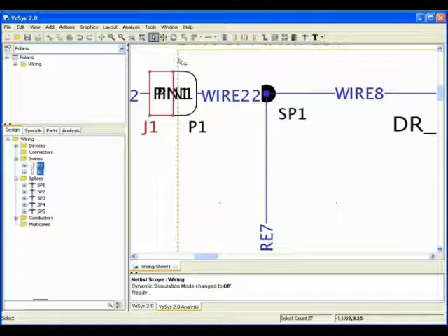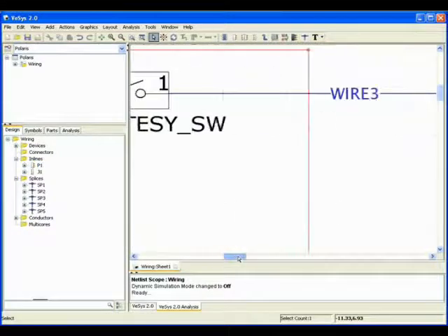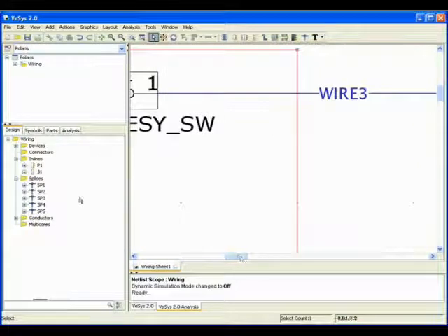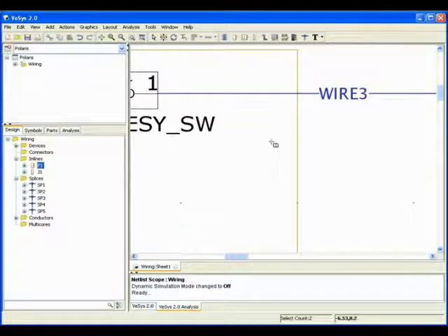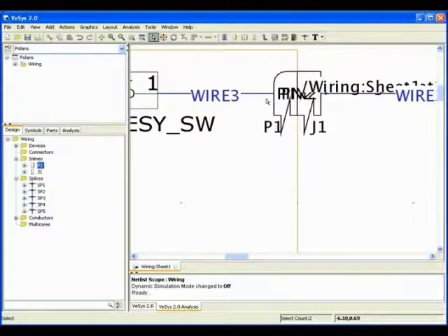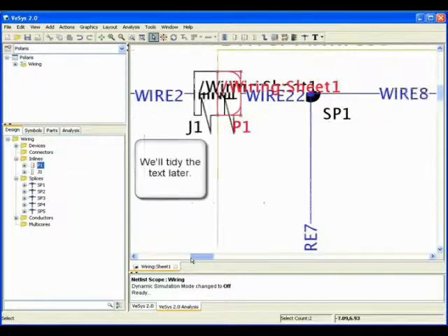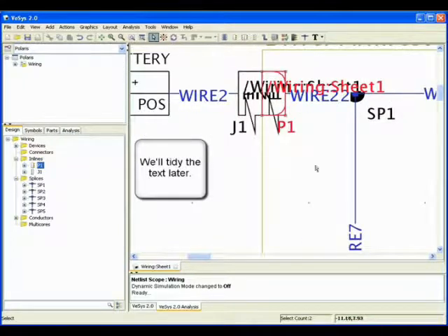To insert the inline on the next wire, wire W3, we double-click on P1 in the Design Browser tree and click on OK on the pop-up dialog. We create the receptacle outside the rectangular boundary and the plug on the inside. Notice how the connector symbols show a zigzag symbol. This indicates the same connector appears elsewhere in the diagram.